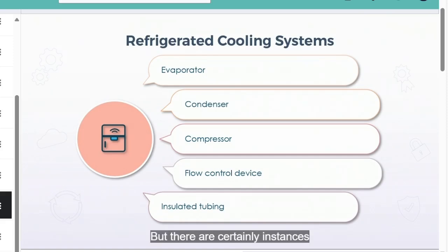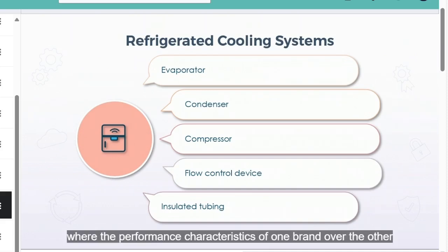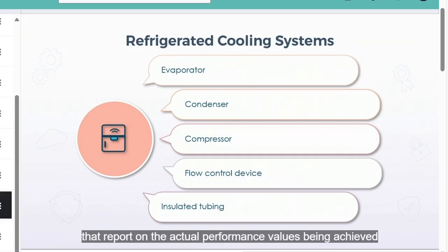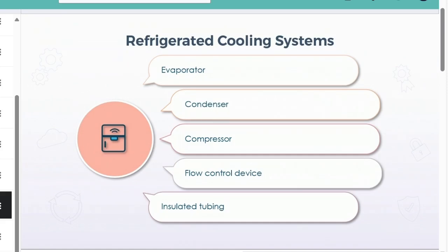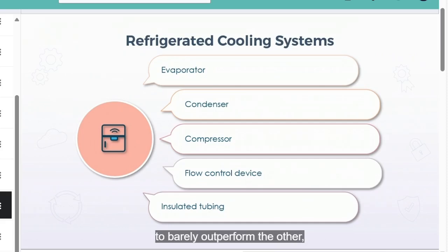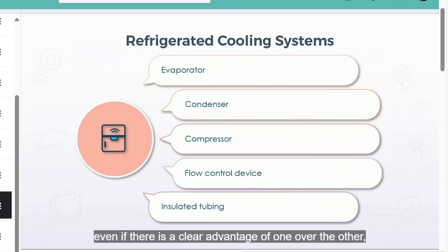So given the increased complexity of refrigerated cooling systems, they aren't particularly commonly found except in very particular situations. But on the topic of refrigeration, I should also mention standard air conditioning, which is very commonly used in large data centers that house many servers and networking components in a single place. Simply having so many devices in one location that all produce heat will likely produce an excessive amount of heat in that room. So if the overall ambient temperature can be kept as low as possible by using air conditioning, the devices will stay inherently cooler because they would all have fans that draw in air from the surrounding environment. So the cooler that air, the more effectively those devices themselves can be cooled.